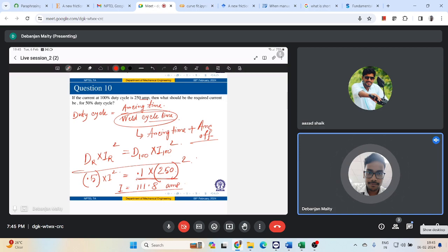Your power source can supply 400 ampere for 3.5 minutes in every 10 minutes. So I am saying that it can supply 400 ampere at 35% duty factor, for 3.5 minutes in every 10 minutes. 3.5 by 10, that is 35%.